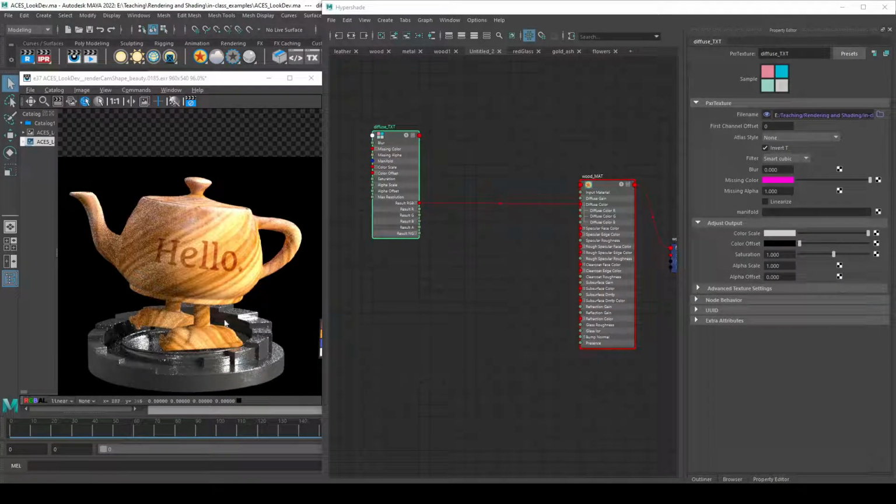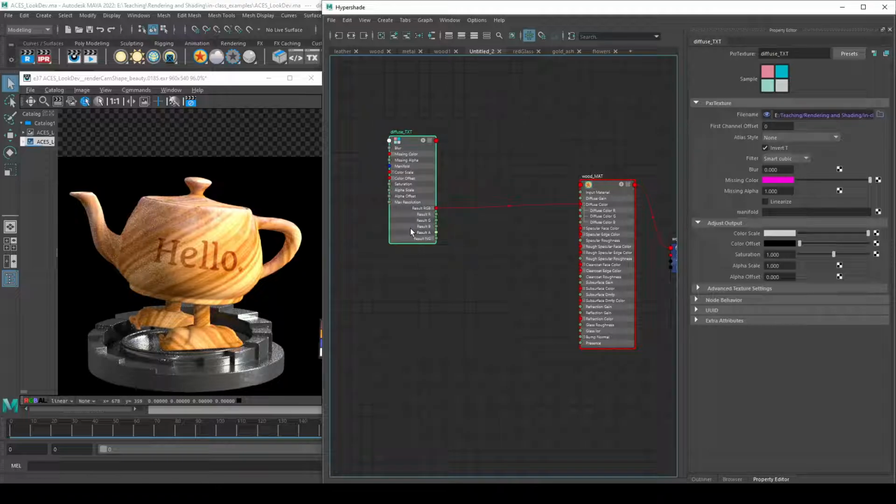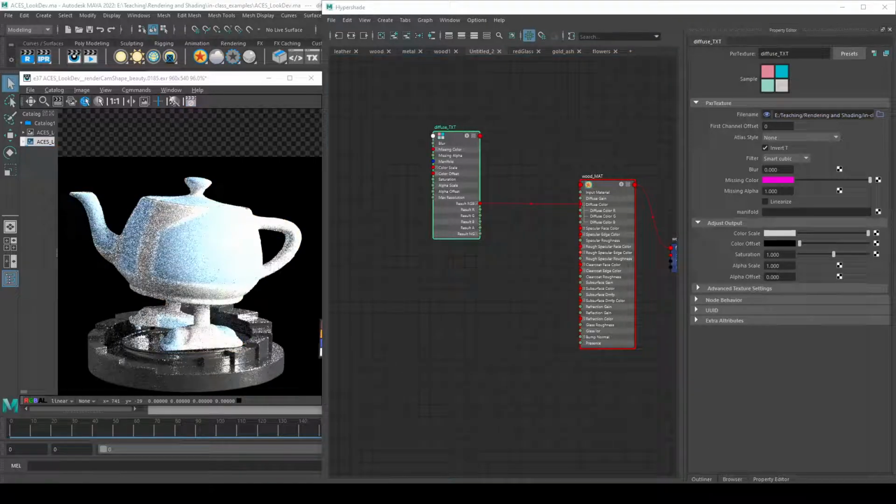Okay, so I went ahead and loaded the texture. Sometimes you'll see it kind of have like a blue color. Let me go ahead and see if I can get that pulled up really quickly. So I had to stop it before I converted it. I just want to show you what this looks like. Sometimes you'll see this gray image and it has like a blue R on it. So this just lets you know that RenderMan in the background is still processing your texture map. So it's not ready yet. It's still loading it in.